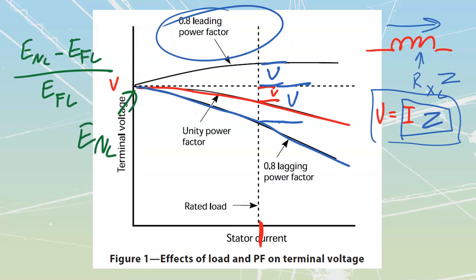That in a lot of cases is actually going to be larger, higher than what I have for my rated full voltage. This is my rated full no-load voltage that I would have there. Obviously, it's going to be a very dangerous thing to go into an overvoltage. Insulation starts to break down. We start having issues as a result of that.